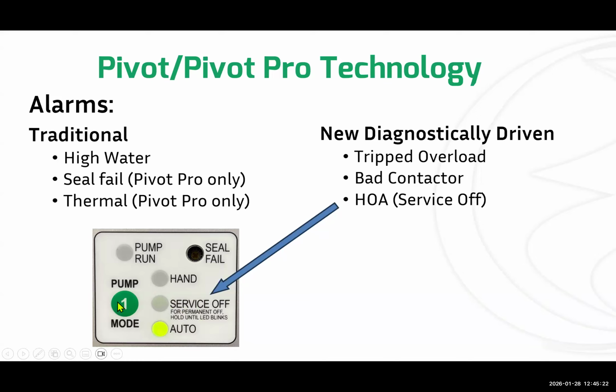It's not going to sound an alarm. It's not going to call that pump to run. It's just like the old style hand-off-auto switch. If you put it into off, it's just going to ignore that pump. It's like it doesn't even exist. So we have the ability to do what you've always done, which is take that pump out of service for a long time.